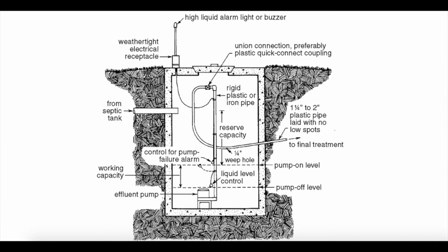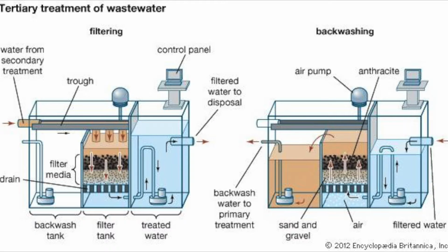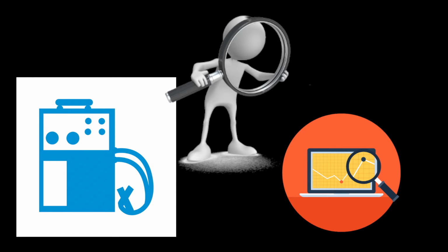Clarified wastewater will then gravitate to the tertiary filter feed pumping station for final treatment and flow to the final effluent pumping station. The tertiary filter is periodically backwashed using treated wastewater. The wash water is directed back to the forward feed pumping station. A sampler automatically collects samples of the treated effluent for analysis.